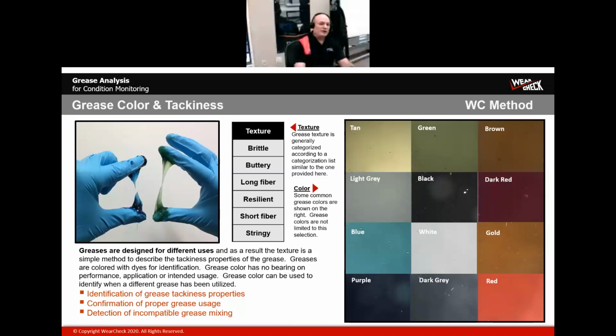It shouldn't become brittle. That texture is also important if the grease itself starts to become brittle and feel dried out. Obviously that's an indication that we may have an incompatible grease mixed in there, or that we may have no lubricant left in the grease.